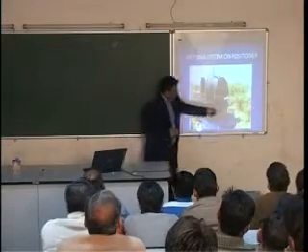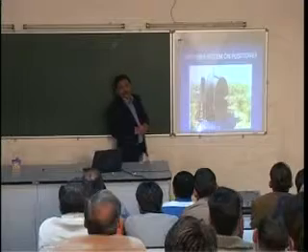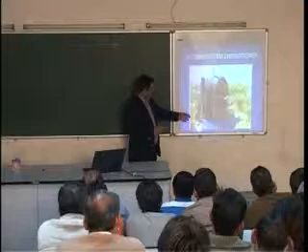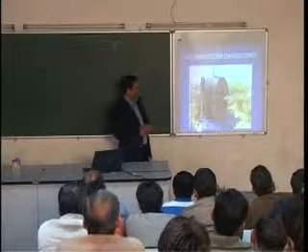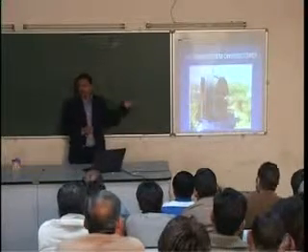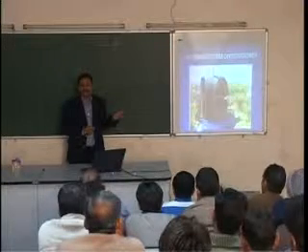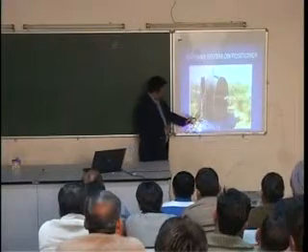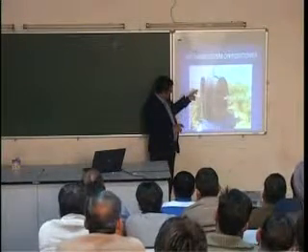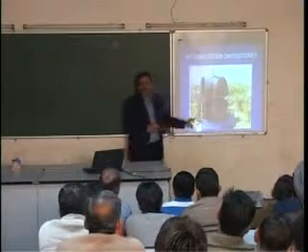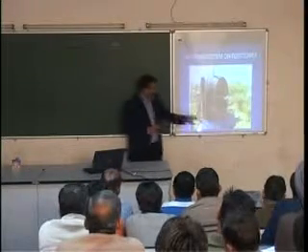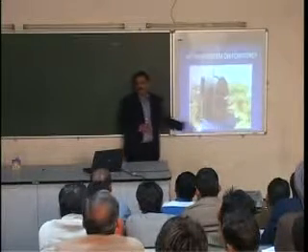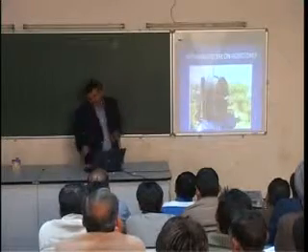Even these trees which are there, they are good observers and they give a reflectivity in an arbitrary direction. But sometimes when we are talking about 30 dB and 35 dB, these also generate the noise which does not allow you to characterize your antenna properly. So you are seeing even this fixture which is used to mount the antenna can also give you reflections, and that is why the designer team have put some absorbers here so that these signals can be absorbed.